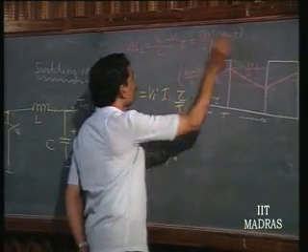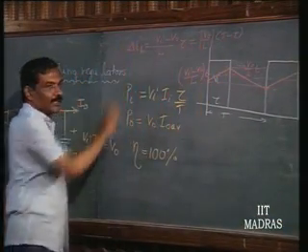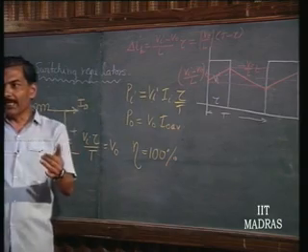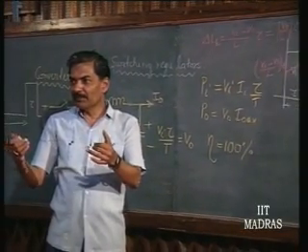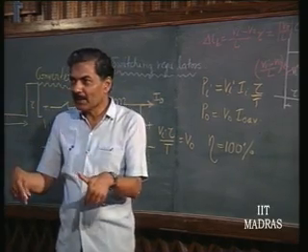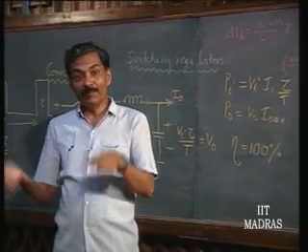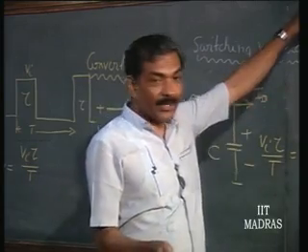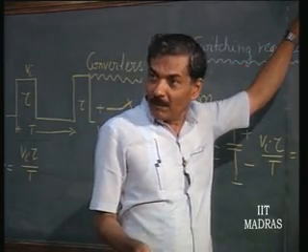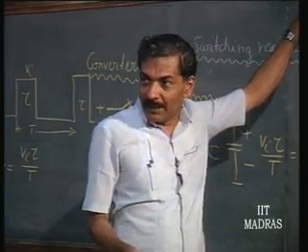So, this is important, this change in current. Normally in a good design, if you want the ripple at the output to be small, delta IL itself should be small. This is the change in current which will be flowing through a combination of resistor and capacitor. If this itself is made small, the ripple will be smaller. So, how do you make ripple small?